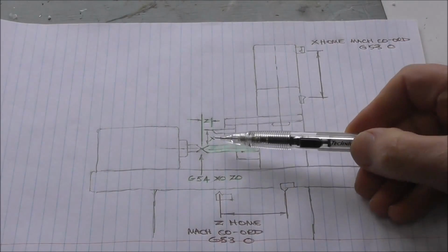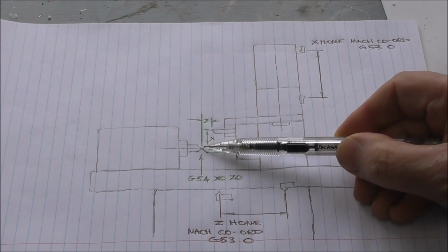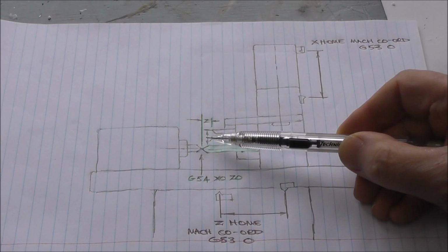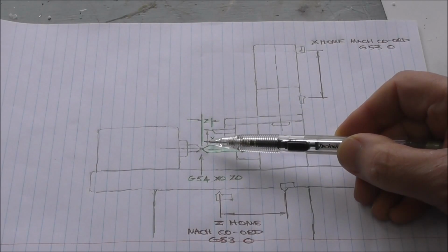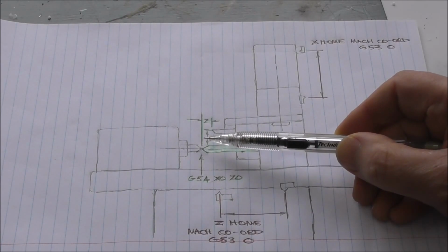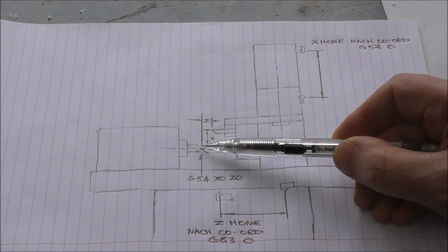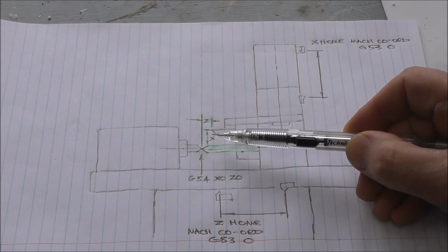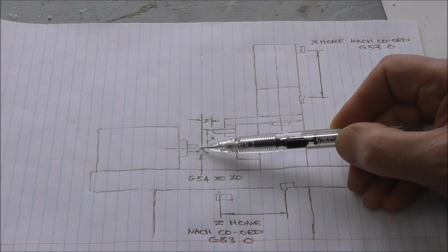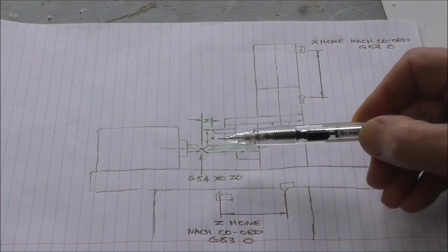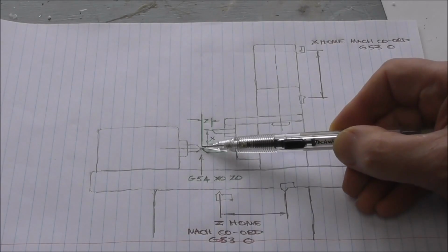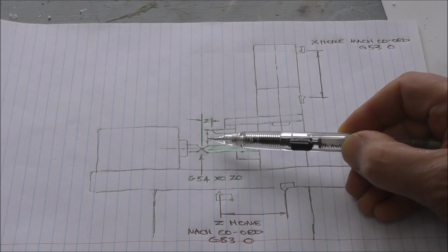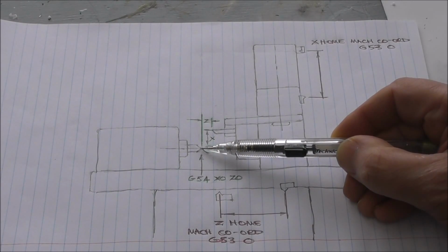Alright, now let's say we've got a master tool that's a pointer. If you're watching Mike Corliss's video, he uses a corner of a tool holder. When our master tool or tool holder position is touching the end of our work, that's this position here, we say our G54 work offset is set, and our G54 coordinates are x0, z0. That's the G54 0, 0 position. We could call this our operator's home position, or our operator's referenced position.